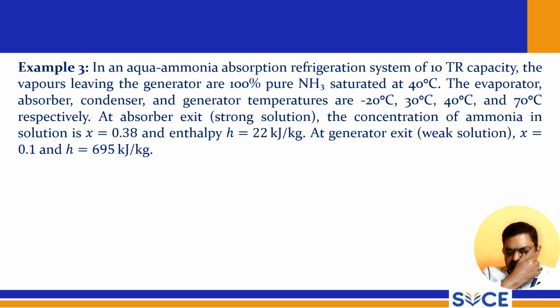So then next problem, in an aqua ammonia absorption refrigeration system of 10 TR capacity, the vapors leaving the generator are 100 percent pure NH3 saturated at 40 degrees centigrade.